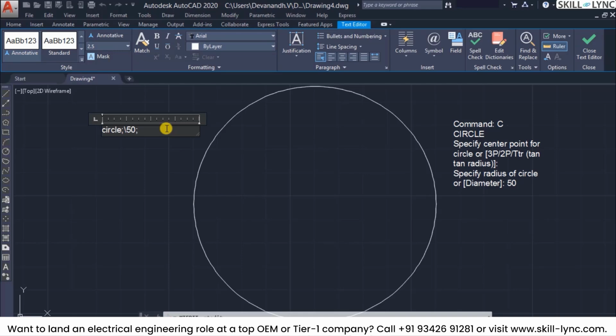But one other thing: this executes a macro, but there might be certain conditions when some other command would have been running before we execute this macro. So in order to make sure that any existing running commands are cancelled, we prefix this command using the caret symbol C, caret C again. This caret C means cancelling.